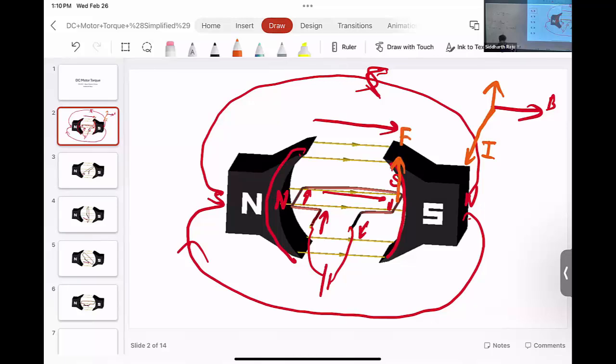What is going to be the force on the conductor on the left? It's going to be downwards on the conductor on the left. Downward, thank you. Because previously the current was coming out of the page, now the current is going into the page. So basically the current direction reversed, you can just put a negative sign for the previous case and the force would end up being downwards. So what we have created is effectively force on two conductors.